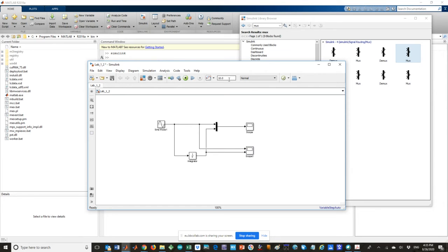Okay. By default, we have 10 seconds here for the simulation time, but we don't need that. These 10 seconds, I'll keep it now just to show you what will happen. But after that, we need less than that. And I'll show you how to calculate the simulation time if you like. Okay, I launch this. We'll get some signals. Those signals will not be perfect sine waves. I need to show you that they are not perfect sine waves, and after that show you how we can smooth them to make them more like a sine wave or a cosine wave.